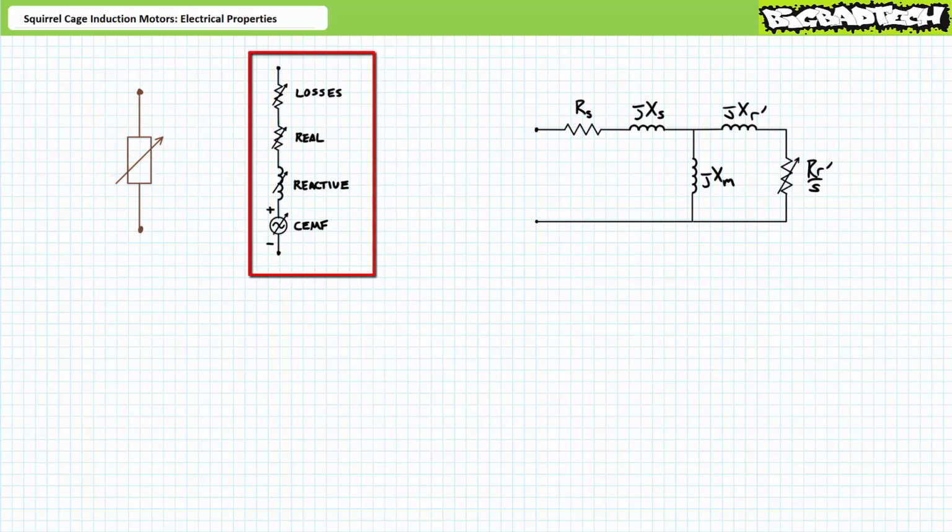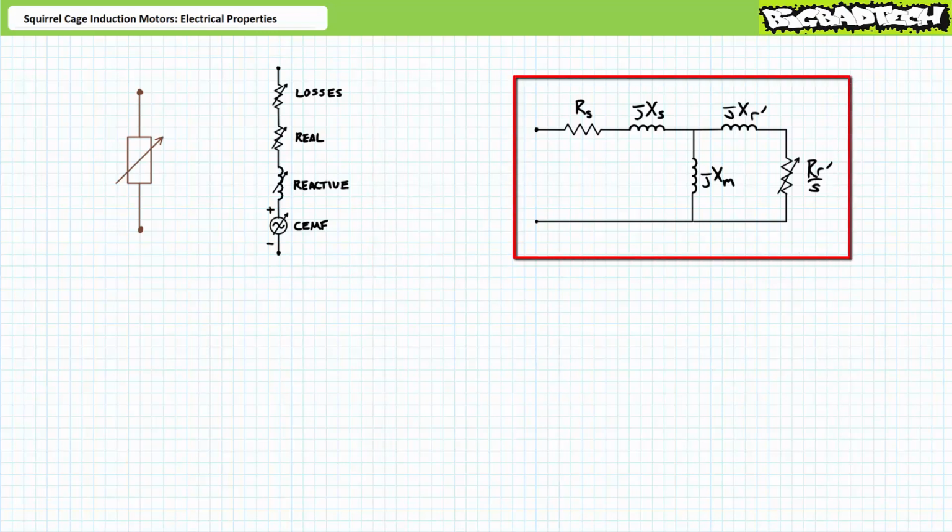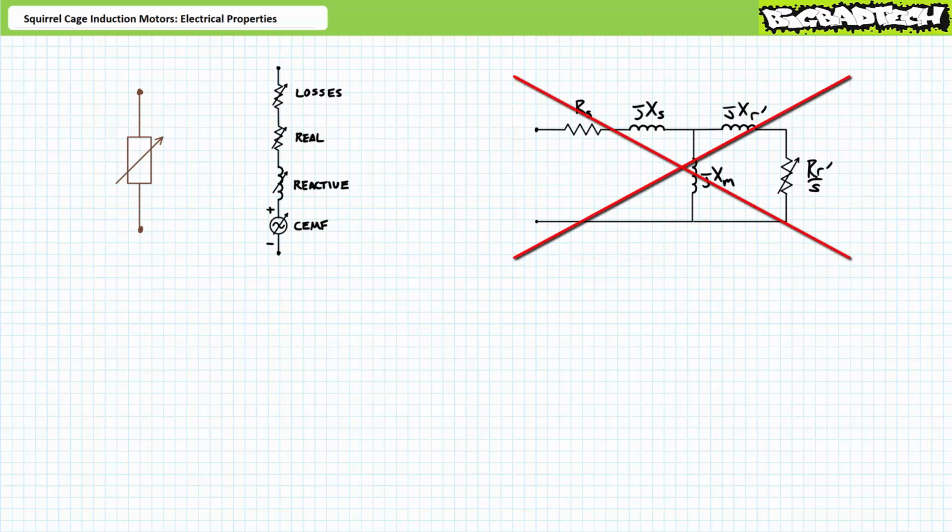The more complicated, not so easy method visualizes each winding as different impedance components in series with a variable voltage source in opposition to applied voltage. This method takes a little bit more effort, however it yields more usable results. The super hard method uses the Steinmetz or T-equivalent circuit, consisting of a series parallel combination of stator resistance, leakage reactance, reflected rotor resistance and rotor leakage reactance, slip and magnetizing reactance, using super confusing calculus that incorporates functions of flux density, torque, and other things that are best ignored. Ain't nobody got time for that.